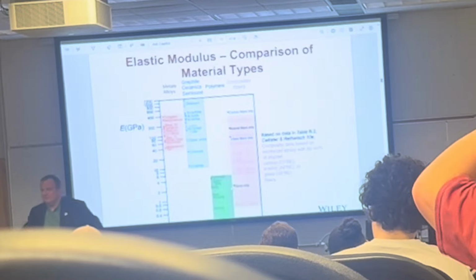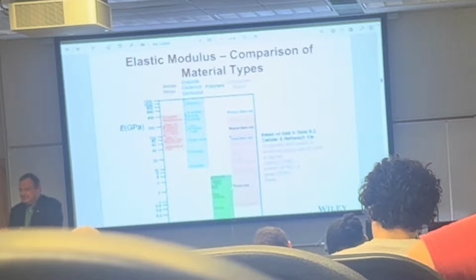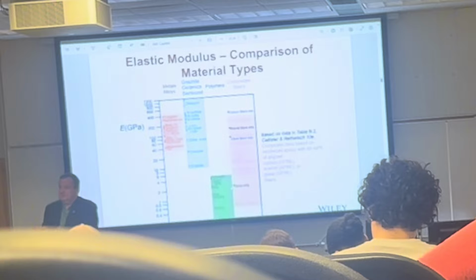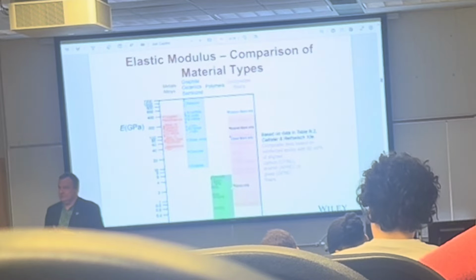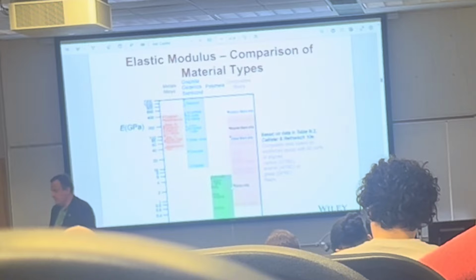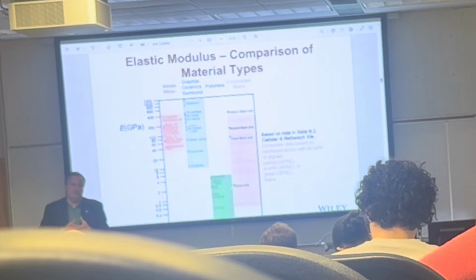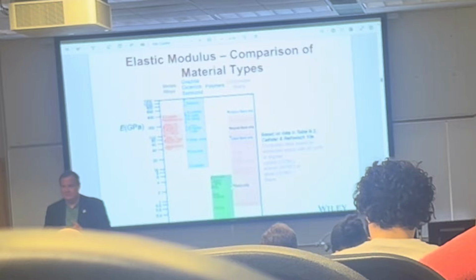The reason I'm asking you is that if you have this material, there's really no way to change its elastic modulus. We will talk about alloying. So when you take 50% copper, 50% nickel, and you make an alloy, then the alloy elastic modulus would be different than nickel or aluminum. But once I give you a chunk of metal, and we're at room temperature, it doesn't change that much.